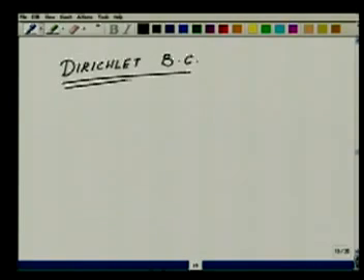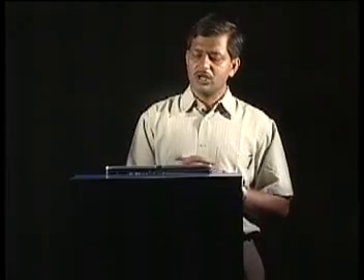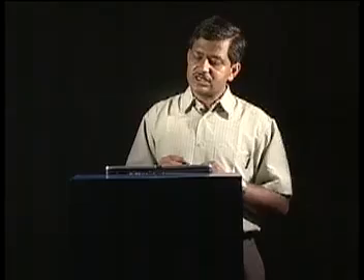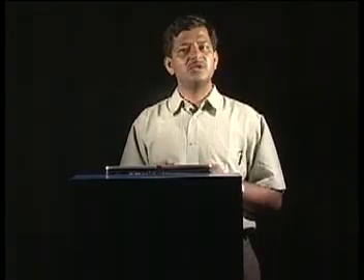This is a little bit more involved, and we have not yet applied it in a problem. We know that out of the Dirichlet conditions, u1 should have been 0. So how do we impose u1 is equal to 0? So once we have done this, then we have essentially given the outline of how to go about doing a finite element computation. And also I have given you hints as to how we should progress with the programming of all this in a computer program.